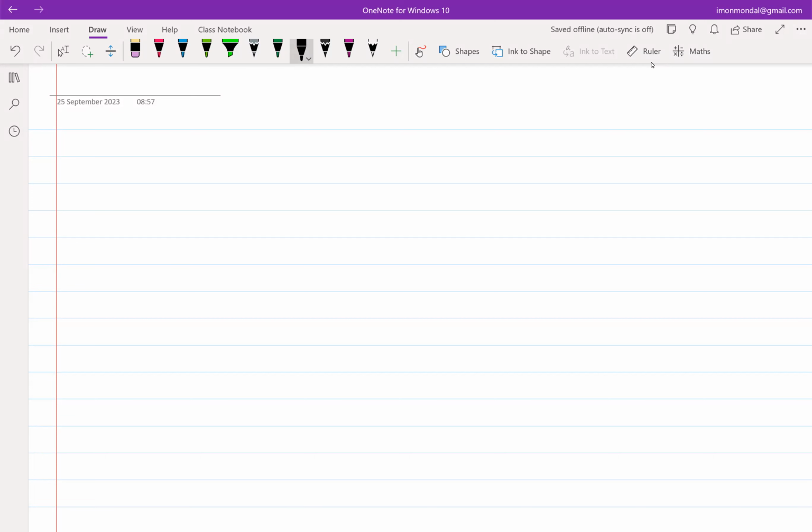One of the issues of the common source amplifier, and it has many issues, but one of the major issues in the context of making an amplifier is that even though you can get a decent amount of gain, the gain is directly dependent on the load resistance RL, right? So that is a problem. Why is that a problem? Because often the load resistance is not in your control. It can be a variable load resistance also. So if the load resistance varies, then obviously the gain varies, right? So that might be a problem.